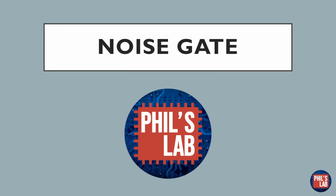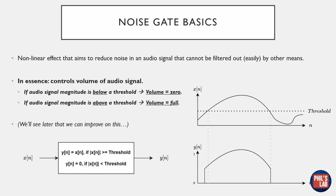In this video, we'll be looking at the noise gate digital effect and how to program one yourself on an STM32 based microcontroller. The noise gate is the first non-linear effect that we'll be looking at. In essence, this effect aims to reduce noise in an audio signal that cannot be filtered out easily by other means, for example by low-pass filtering or band-pass filtering.